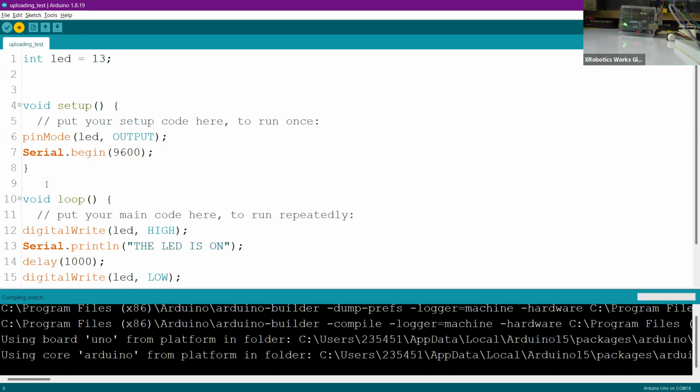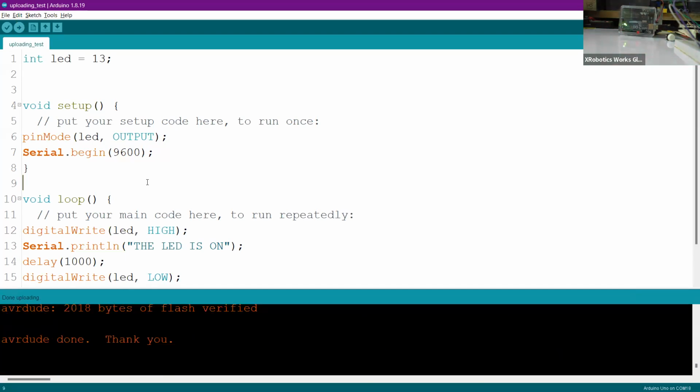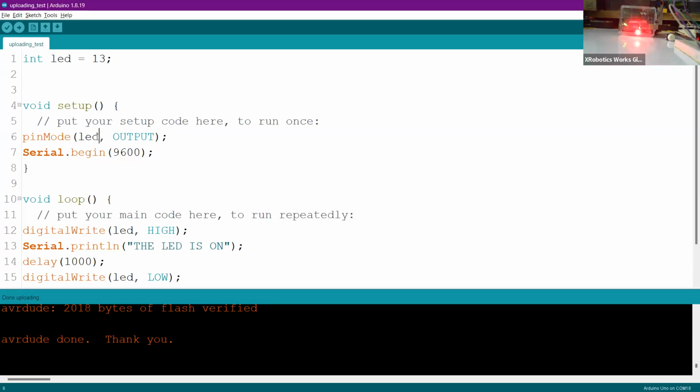These are the methods to be implemented while programming Arduino boards, because sometimes, suppose you are writing the program for your car or something like that, and suddenly you change your mind to replace that particular pin with another pin. Then you would have to either search and replace, or do it manually for each and every place you mentioned the pin number. But through this method, if you call a variable and directly assign the value to it, that is, I'm calling the variable LED to represent pin number 13, right? Now it is much simpler for me to integrate the LED on any other pin.